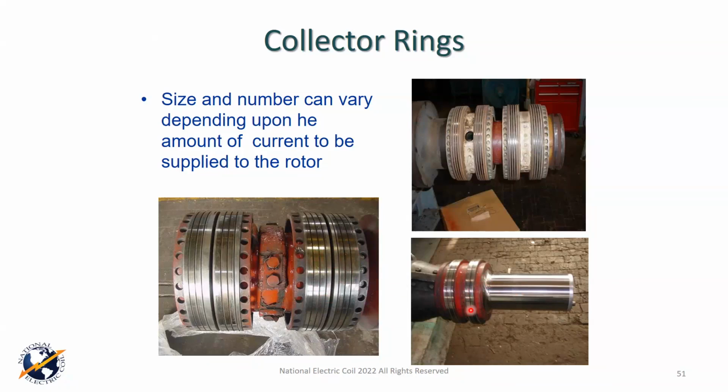And people always ask me, well, what's the matter with that one? It has all those holes on either side. And again, if we were all together, I'd ask you, what are those holes all about? Well, you have a lot more current because of these tandem rings, and these are pretty large ones up here. Those holes are actually maximizing surface area to help keep the ring surface temperature cooled, okay? The hotter you make it, the more you can interfere with the brushes themselves and the commutation. So those holes are nothing more than a cooling vent, and they give you some cooling into the ring itself.